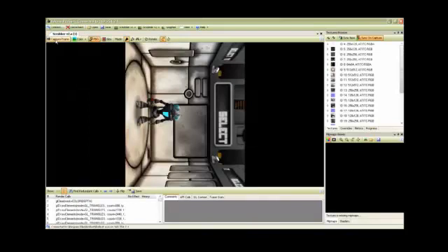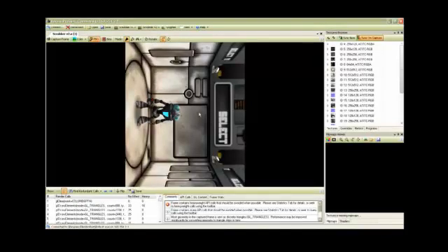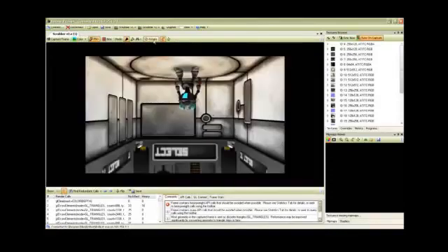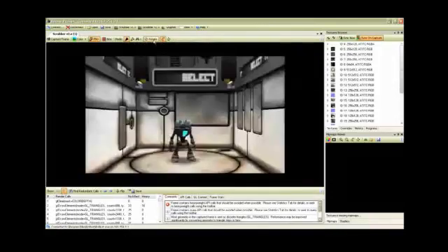So this takes a few seconds, but what happens here is within the OpenGLES driver, we've introduced a shim layer, which allows us to intercept all of the OpenGLES API calls. And so not only are we able to capture the calls themselves, we capture all the parameters and all the data associated with those calls. So what that allows us to do is to recreate the scene on your PC using our OpenGLES 2.0 emulator. And through doing this, we're able to provide really detailed analysis of what's going on in that frame, look at all the individual calls and all the states associated with that. And so that's what you're seeing here.